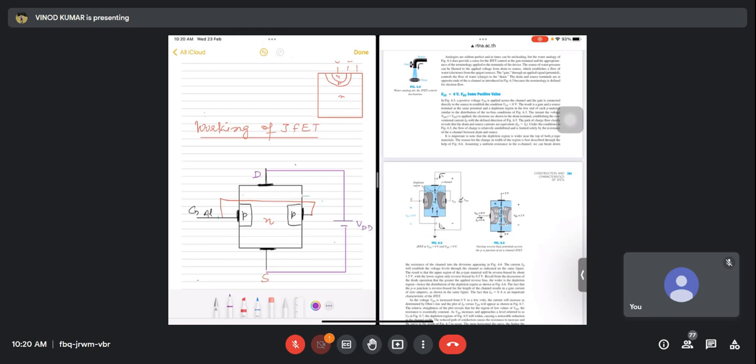Right? It means this is variable, positive potential here, negative potential here. This is connected with ground, you know. Okay, and this VGS is also zero. Means both are connected with ground. This is also at the same potential, ground. So VGS is zero and VDS is positive. This is the first condition which we are taking.